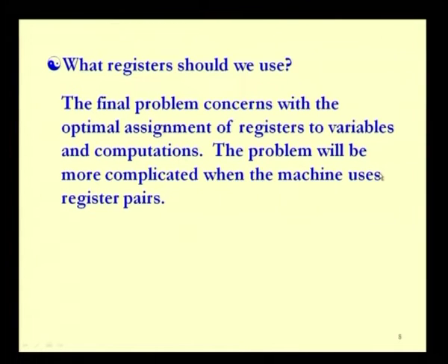And another thing is that sometimes machines will have register pairs. In the 8086 and 8085 microprocessors we see the BC pair, DE pair, and HL pair. When we combine these pairs, we will be able to handle larger data values; rather than 8-bit data we can even handle 16-bit data, or rather than 16-bit data we can handle even 32-bit data. So, instead of doing the computation in parts, if you have a mechanism for computing them in a single instance or by using a single instruction, that will always be advantageous and it will take very little time for producing the results.